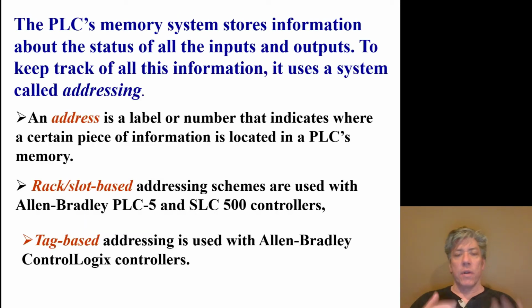So the status of all the inputs and outputs has to be stored in the PLC's memory, and the way you keep track of it, the way you figure out which particular little bit of memory corresponds to which input or which output switch or device, is by addressing. And addressing is just a number or a label that indicates where that particular input or output is